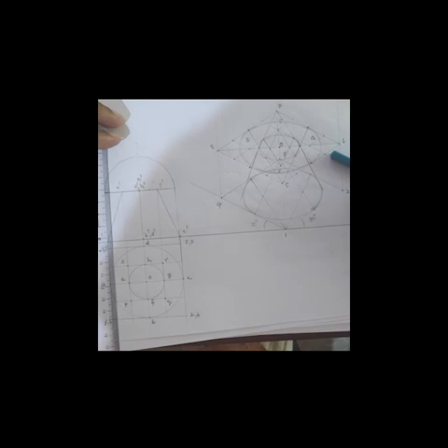And the only thing that you have to complete is the curved profile. And what is the radius of the curved profile? For obtaining the radius of the curved profile in isometric view, you have to divide the actual radius with 0.816.